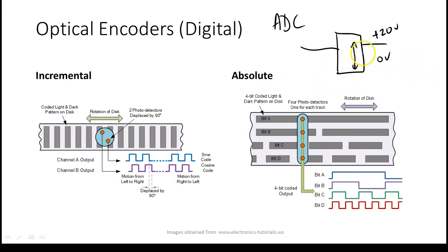So this is what I'm saying. These digital sensors are great, but odds are what it senses is analog. So light, is light digital or is light analog? Could be either one. But normally the sensor itself is analog, and we run it through a digital A to D converter. And we set what they call the sensitivity, but basically it's the threshold of where it switches between a true and a false. Every one of these light sensors over there has a tiny screw that, if you look real close, you could turn to change the sensitivity.